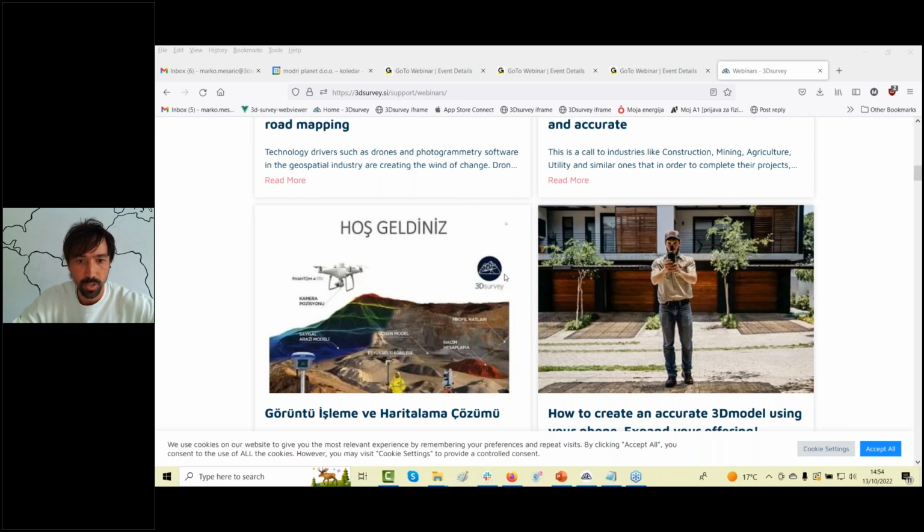Let's go to Sophie. Sophie is asking, can we use this videogrammetry in addition to an existing point cloud? Example, I missed some details and someone sent me a movie instead of going back to the site. Yes, it's a question connected with the previous answers. You could do that, of course. You can also process it separately, and then with the combination of known points, you can orient the videogrammetry result with the drone mapping result.